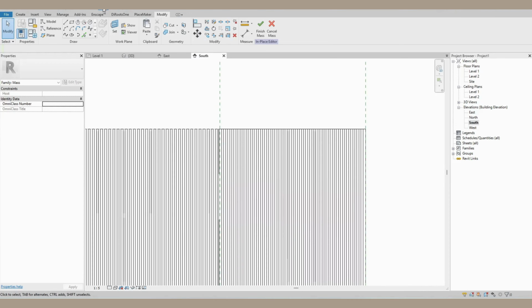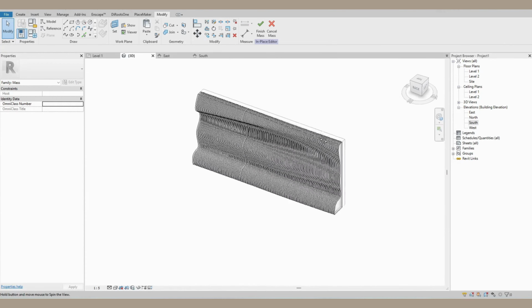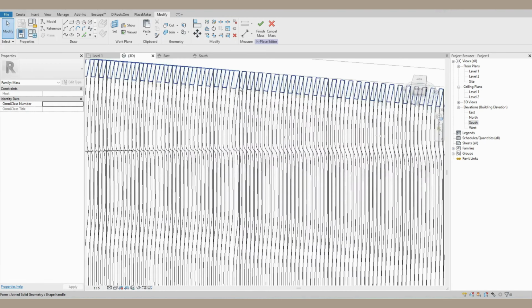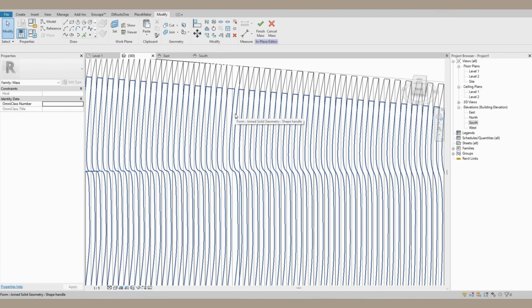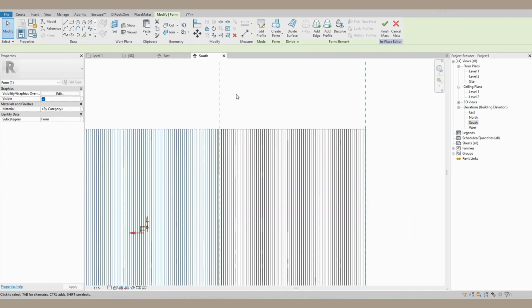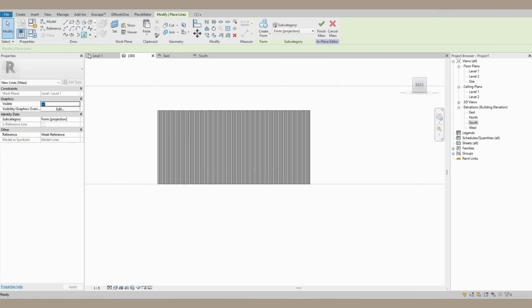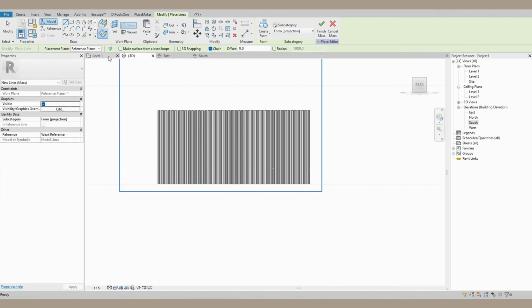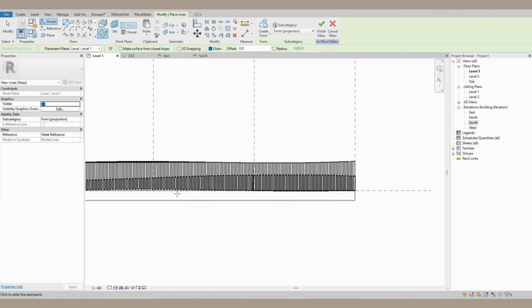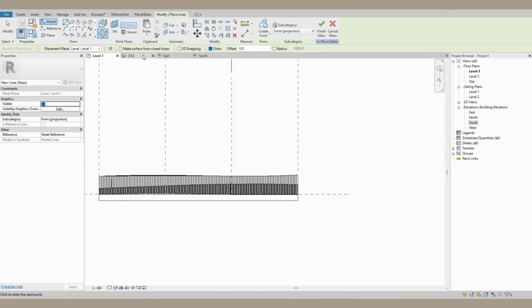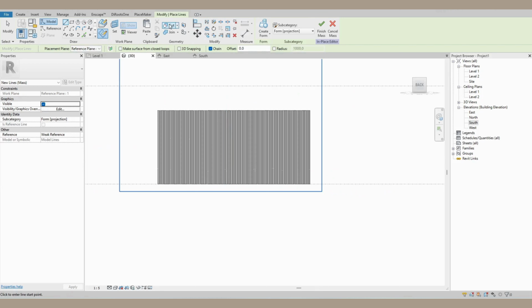Great, and as you can see, the form is almost drawn. We're almost there. This is mostly just to show you how you would cut through a door or an opening. So assuming this is at reception, you probably do have some access hatches, or if the way to the offices is through here, you can use this. And you create a void form as well.